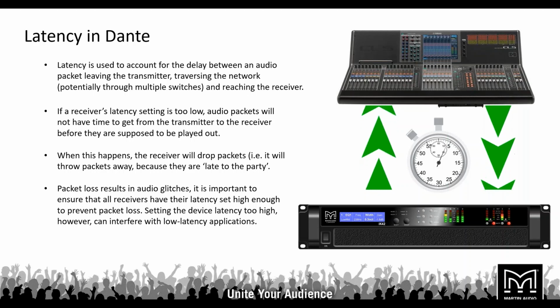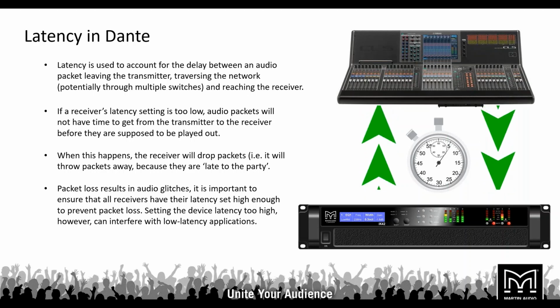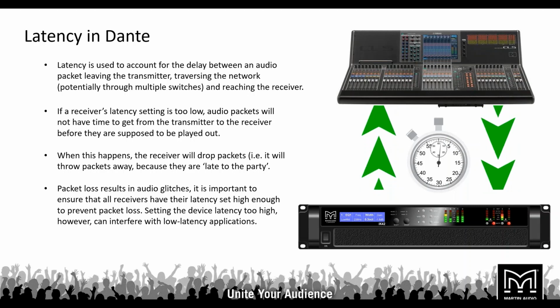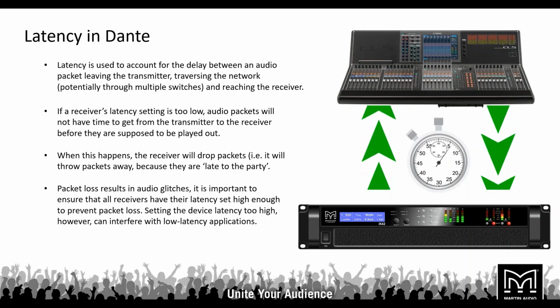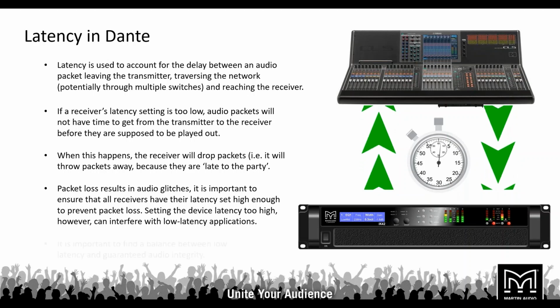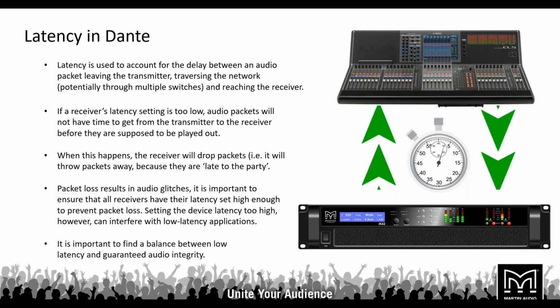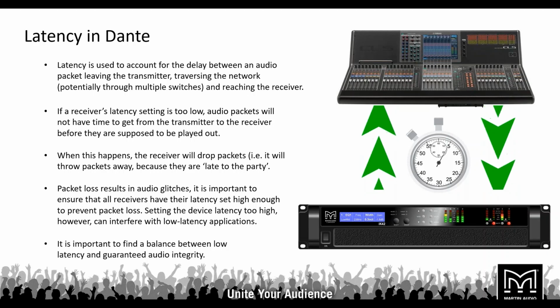It is important to ensure that all receivers have their latency set high enough to prevent packet loss, however, not setting them too high so they interfere with low latency applications. So it's important to find a good balance between low latency and audio integrity.